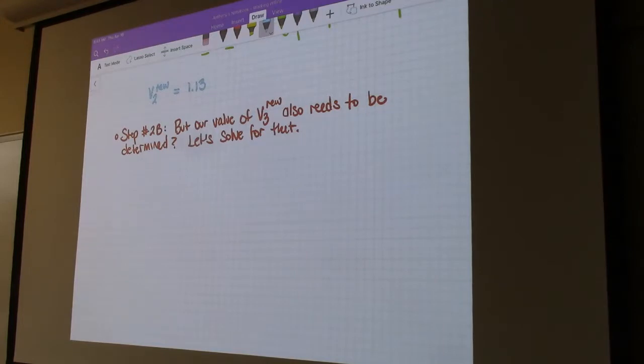We're going to say I3 is equal to P3 injection over V3 old, which is equal to V3 minus V2 over R23, plus V3 minus V1 over R13. This is going to be the new value.